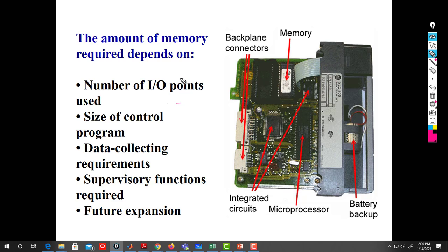For example, a management or supervisor PLC needs more memory because it collects more data and runs a lot of programs. Is there any supervisory function required? If so, you probably need a high amount of memory. Also plan for future expansion, increasing the number of inputs and outputs, so have higher memory.